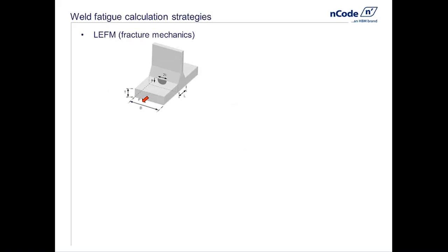Some of the downsides to an approach like this are, one, it's a very point-wise calculation. We would need to have multiple calculations along the entire weld toe, or wherever our weld failure is specified to be. Two, we need to specify the size and shape of the crack as well as its direction. The size is an issue. The initial size for a crack pretty much determines the total life, and with that as somewhat unknown, it's difficult to utilize fracture mechanics by themselves.